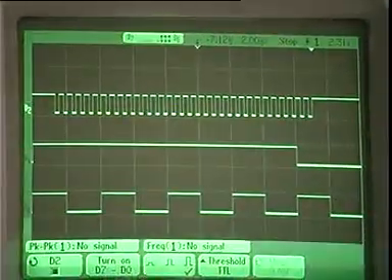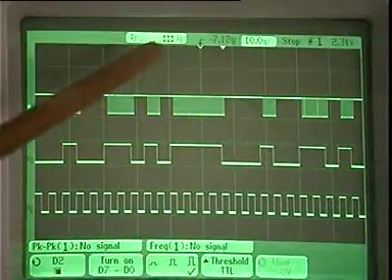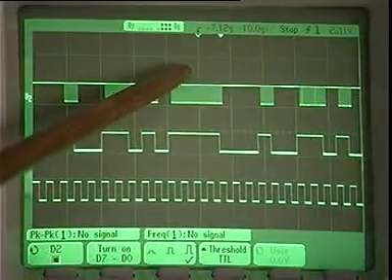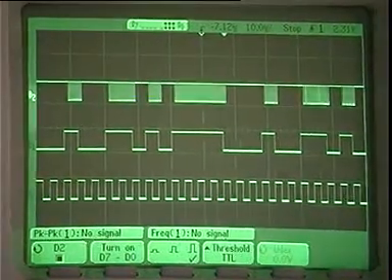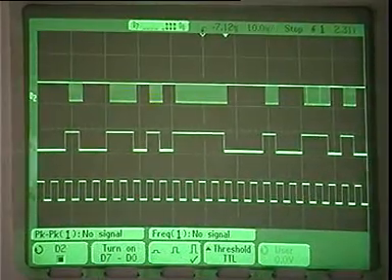So the important thing to realize here is in amplitude shift keying, when I am transmitting a 1, I will transmit the carrier. When I am transmitting a 0, I don't transmit any carrier. So this is how an ASK signal will look. Now apart from the amplitude of the carrier, I can also modulate the carrier's frequency. In the case of a frequency modulated signal, the carrier frequency was continuously modulated.